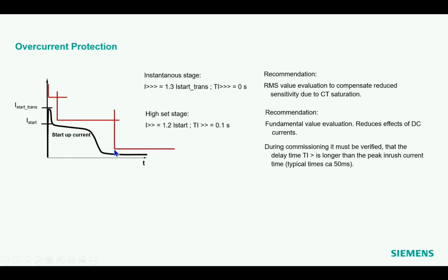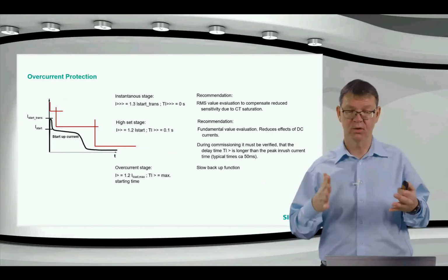Okay, and finally here, this relatively slow backup stage, if at all we can apply such a thing, then we need to be higher than the maximum load current here. Okay, that's how we can apply the overcurrent protection.